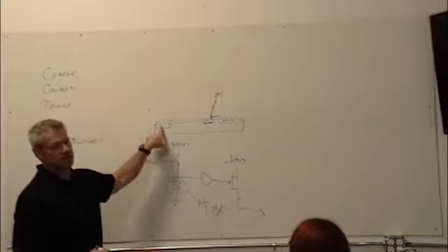But now I've got all this energy here, and I can't put the next one on. Well, crap, right? So I reset it, and I let all those electrons come running out of there, and then I open up my switch, and then I can put the next one in there. And so it's a destructive readout, I've destroyed the whole information as I read it out. It's the clear mechanism on your sample and hold for transfer.